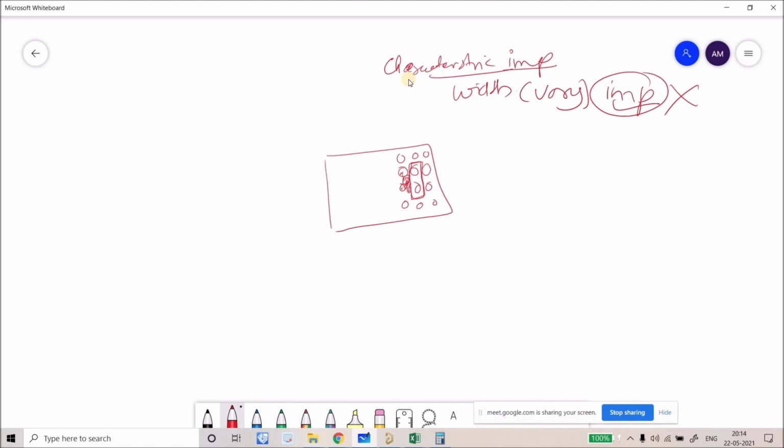So I'm talking about following the clearance here. Whatever clearance rule we have defined, we are following the exact clearance. We are rigid with the clearance. It is okay if we can vary the width. So there's one way. Let's make it thinner, right? Just route it from here, and then outside of the chip, we can again make it thicker. You're getting my point, right? So from here we are following the impedance, but here we have thick connections and here we have thin connections on this end. So there will be two or three impedance discontinuities on this small cross section.